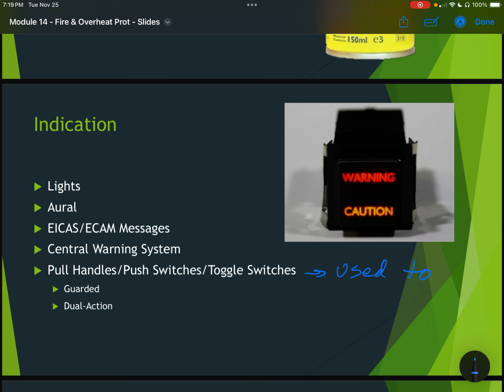to deal with the abnormal situation. And so this is something like a fire handle. So if there's a fire, on a twin engine airplane, typical, this is like a Boeing style, has T-shaped handles. It has one for the left engine and one for the right engine. Then it has a third one for the APU.